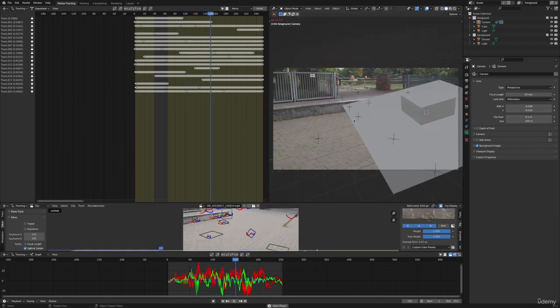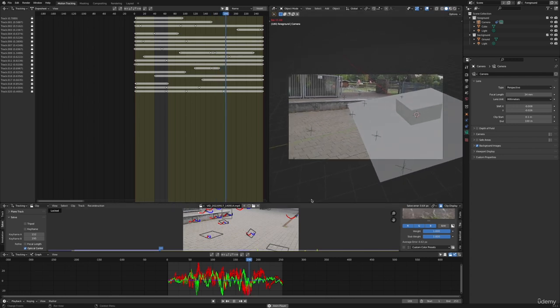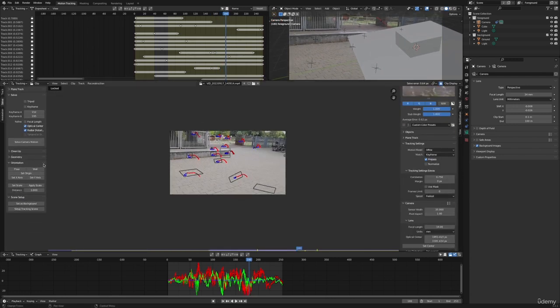The answer to this is very simple. We go to the so-called orientation options down here, and we can now set where we want our world origin to be, so where the center and the intersection of all three axes is.